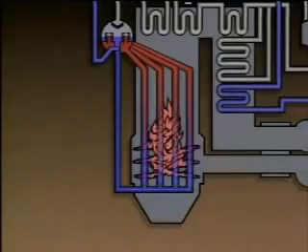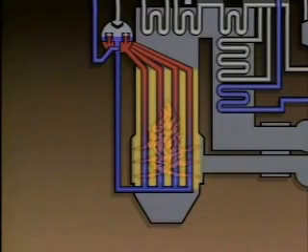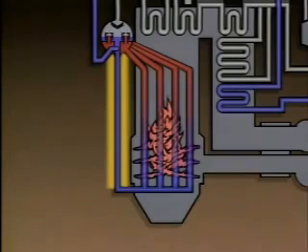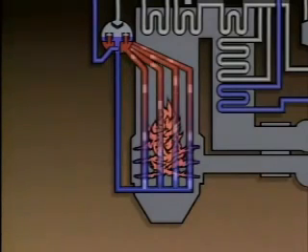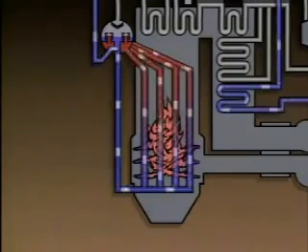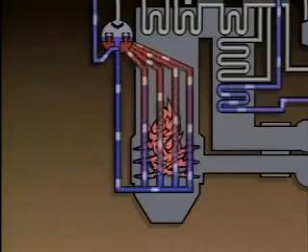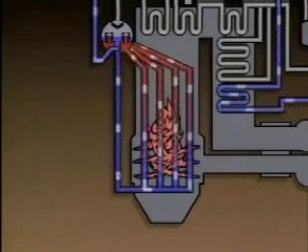The flow of water through some boilers occurs by means of natural circulation. The key to understanding natural circulation is the fact that cold water is heavier or denser than hot water or steam. In a boiler, the mixture of water and steam in the water walls is hotter than the water flowing from the drum through the downcomers. This is because the water walls are heated by the burning fuel in the boiler furnace. As the mixture of water and steam rises, cooler water from the downcomers flows into the lower headers and then into the water walls. The cooler water is also heated and rises, creating a self-sustaining flow through the water side of the boiler.